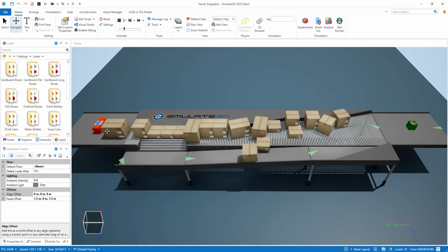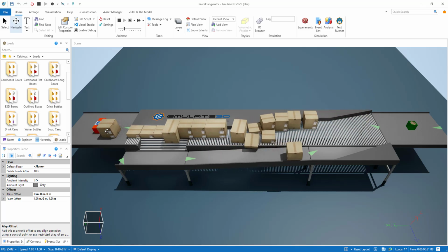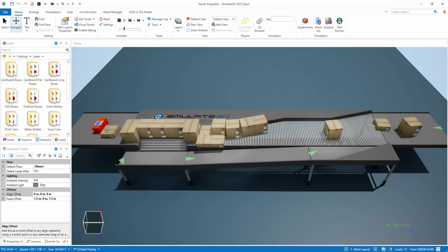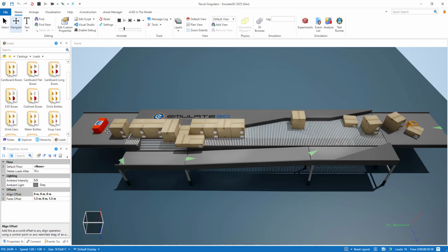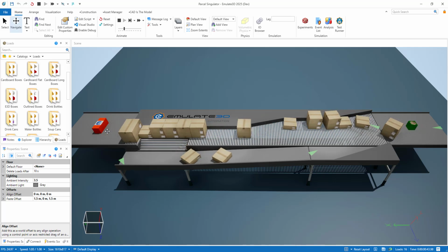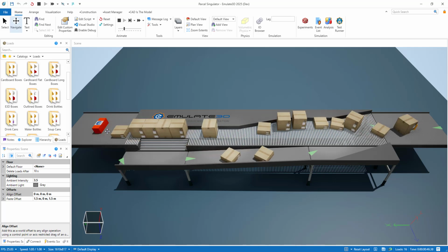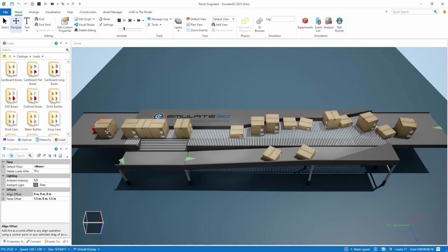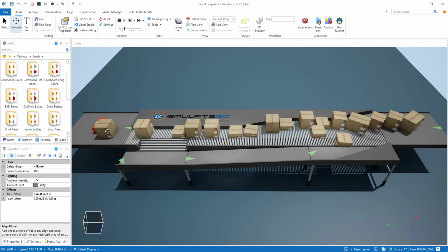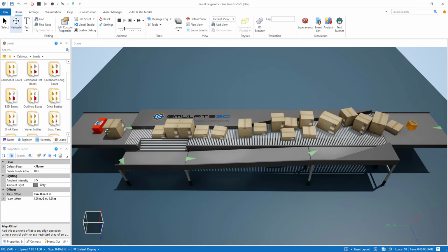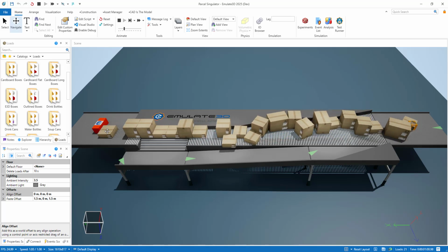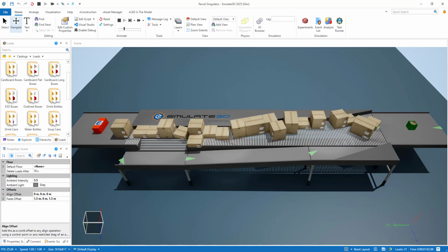So why would we apply version control to this model, and what is GIT? GIT is a free and open source distributed version control system that's going to track versions of files for us. It's going to record changes to those files over time so that we can recall specific versions later on. So you can think of this as, rather than saving a model, we're going to create checkpoints, which we can revisit, and we're going to write a message to say exactly what we did. GIT's going to track who made what changes and when.